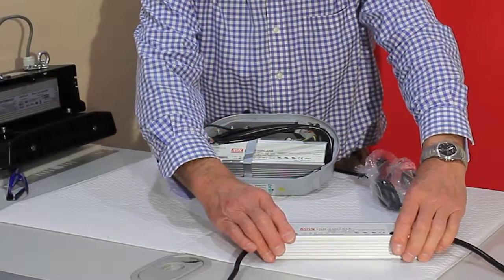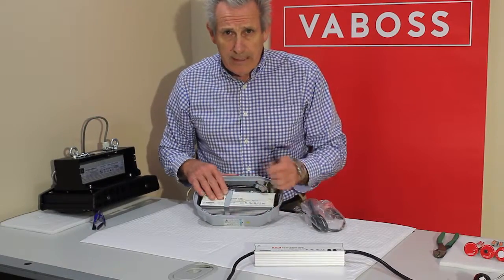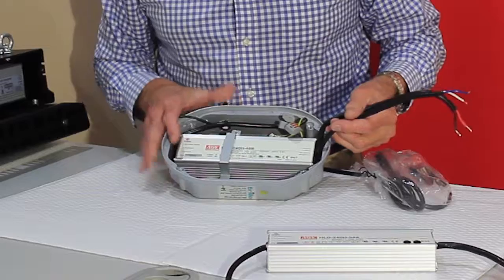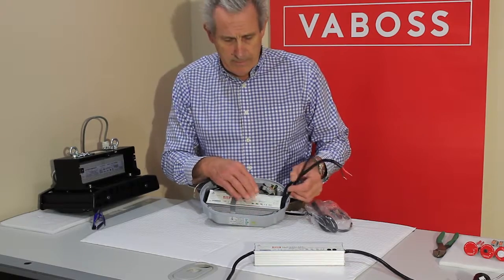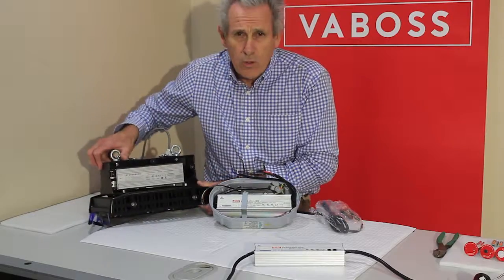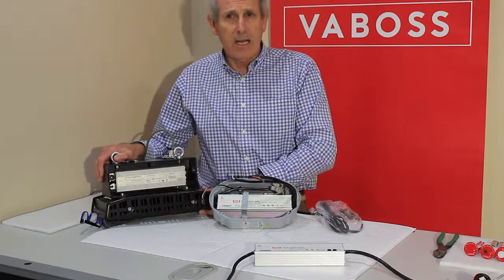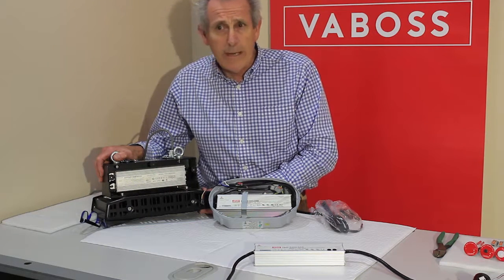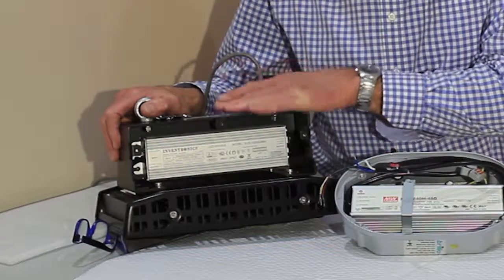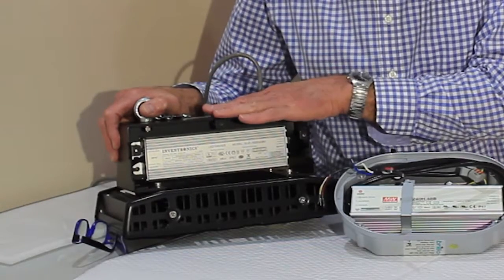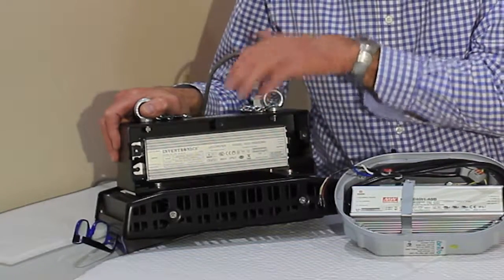But there's another difference. Let's put the standard aside. This dimmable driver is using 0 to 10 protocol. That's the age-old standard in after power supply dimming. There's a new protocol, or another protocol. It's called DALI, D-A-L-I, and that stands for Digital Addressable Lighting Interface. And it's a protocol for building-wide lighting control. This is going to take over the market gradually. It's much smarter, does a lot more, and our control unit can do a lot more with this driver.